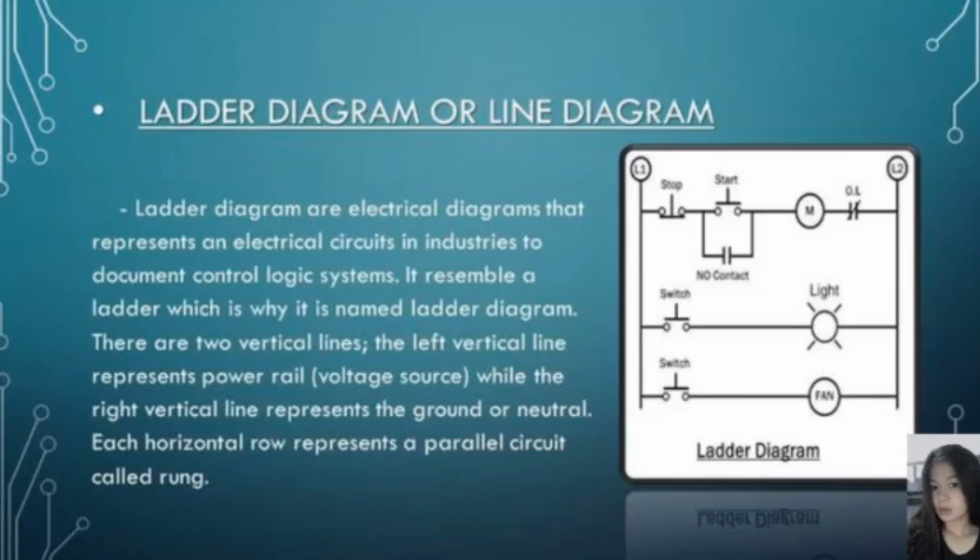The operating voltage for the switch contacts and relay coils in the industrial relay logic circuits will typically, though not always, be 120 volts AC. Sometimes, ladder diagrams are used to build and record lower voltage AC or alternating current and even DC systems.